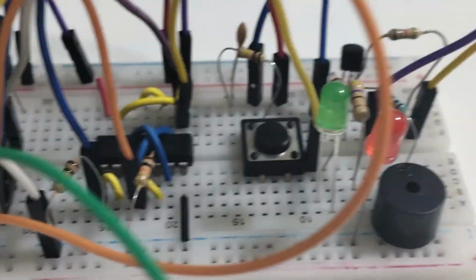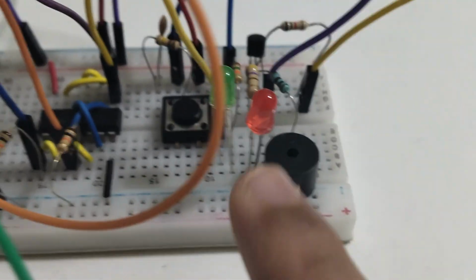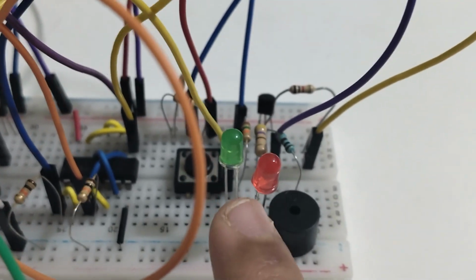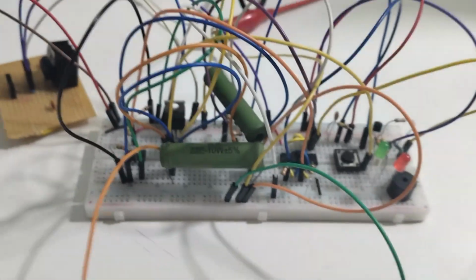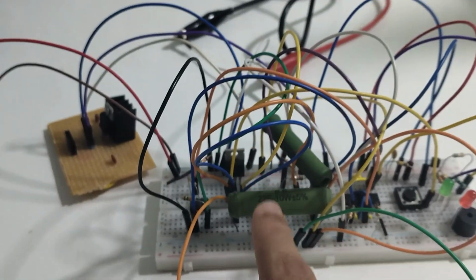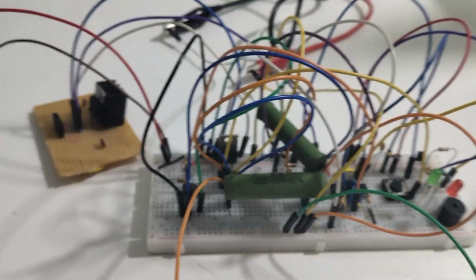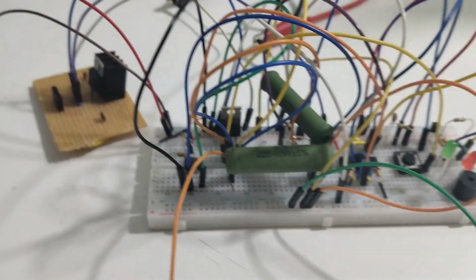As I said, this is the comparator over here, and 150k and 15k set 1.1 volts, so around 1.1 amp is our safe current. And finally, here are the audio visual indicators. If the green LED glows, that means your circuit is operating normally, and the red LED and the buzzer here would indicate the overcurrent. If we divide the load, 12 volts by 22 ohms, roughly 500 milliamps is going to flow, and that's below the 1 amp current limit, so it should work normally.